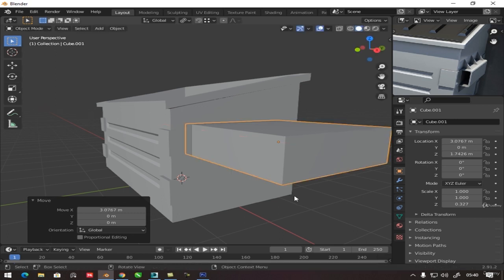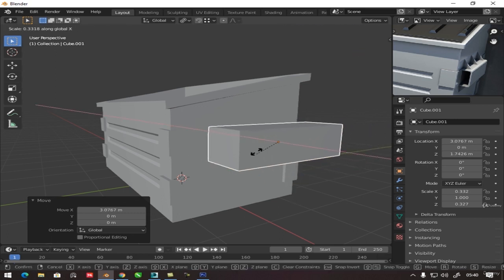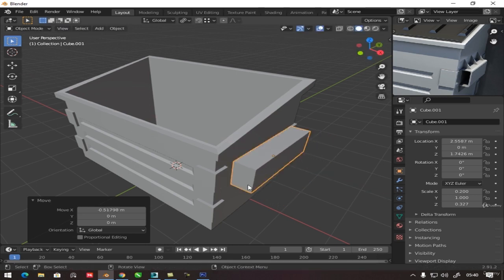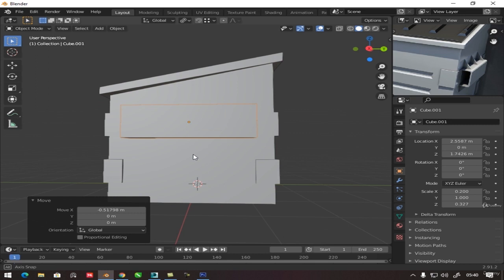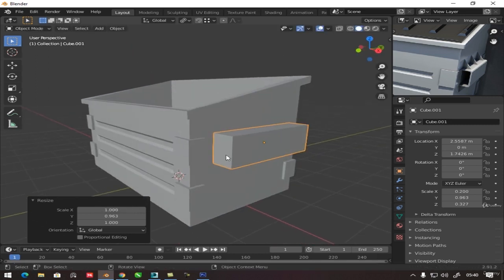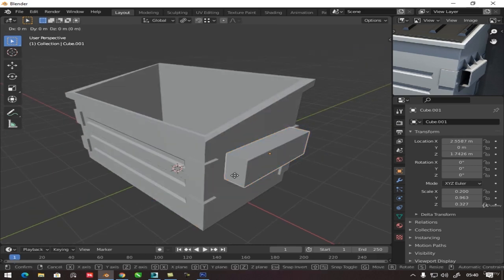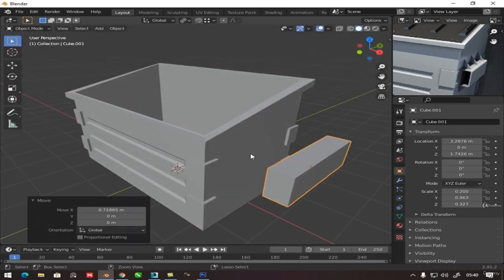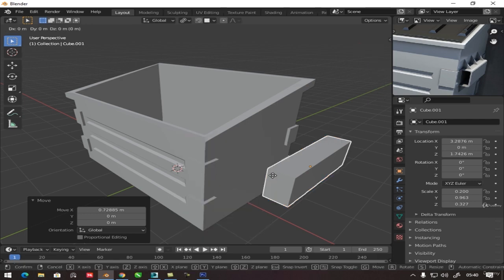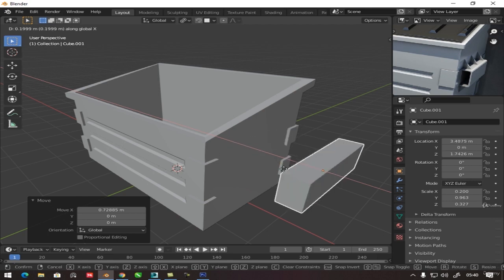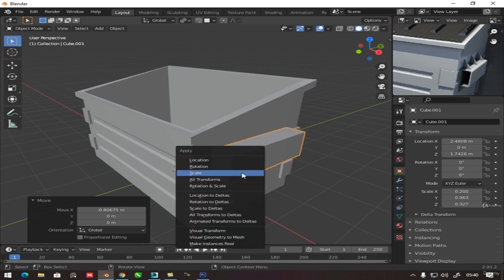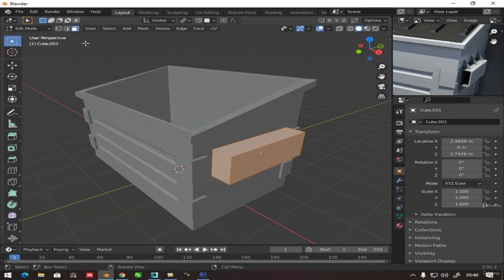And now GY, GX, I bring it to here, SX, I decrease in here, okay, GX, I touch in here, and it's basically this. I go SY, decrease a little bit more, and to touch it here with precision we will do like this. I'll go GX, get a little distance, Ctrl Shift Tab, I can just click by faces, and with Ctrl pressed I can click on the lateral of the container and it will glue there.